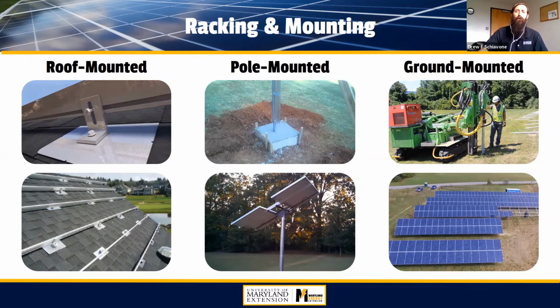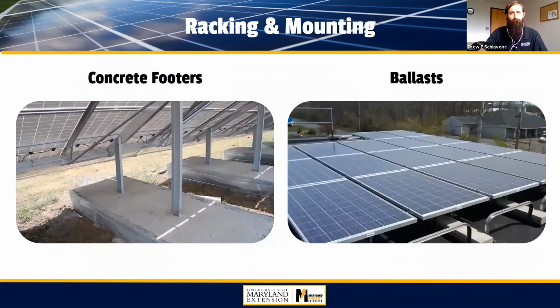Ground mounts are typically larger, requiring multiple piers or piles being driven into the ground. With a larger utility scale, you'll typically have larger machinery, either shaking or pounding or screwing the piers into the ground, and you're going to have more piers based on the size of the system. If it's heavier, you're going to have more supports being driven into the ground. With a smaller scale, you're still going to need equipment. You'll need an auger or something like that, depending on the operation.